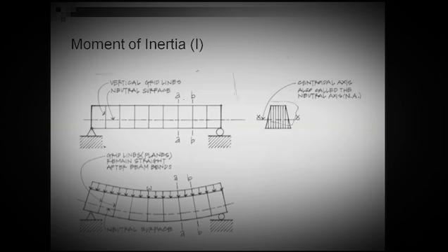All right. Chelsea, you asked me a very good question. Note something: when we are taking the centroid, we use the first moment of an area. Another geometric property we will introduce to you is called Q. It's basically the first moment of an area, and we will use that when we design for shear.